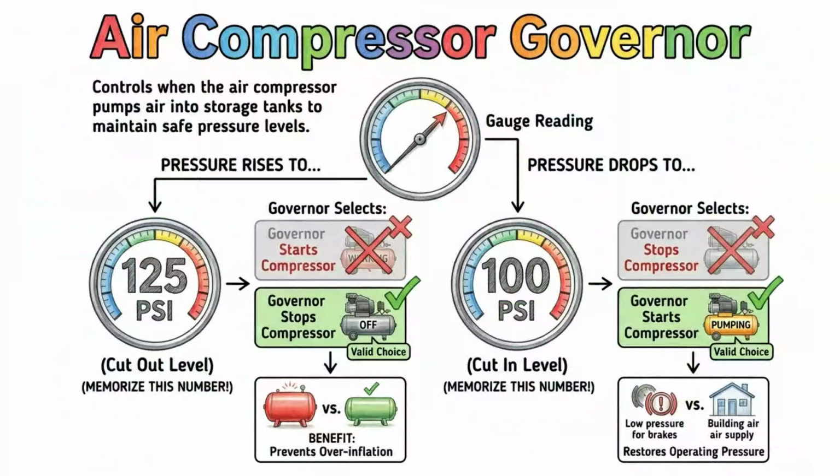These spring brakes are controlled by the brightly colored knobs on your dashboard. The yellow diamond-shaped knob controls the tractor parking brakes, and popping it out applies the spring brakes. If your air pressure drops dangerously low, usually between 20 and 45 pounds per square inch, the system will force this yellow knob to pop out on its own, locking the spring brakes. This automatic pop-out feature guarantees that the vehicle will come to a halt even if the driver completely ignores the low air warning buzzer.